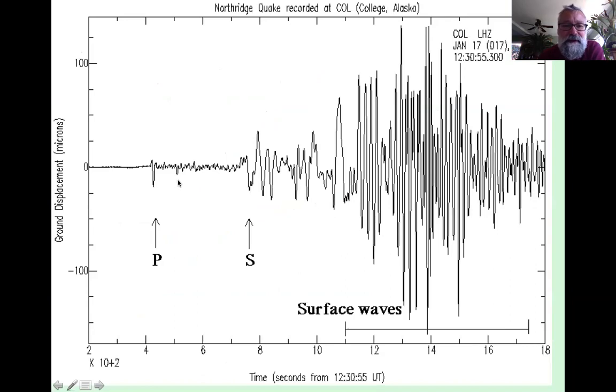This is a typical readout from a seismogram, from a seismometer, and you can see the occurrence of these waves. This is prior to the earthquake. This is the first occurrence of the earthquake, and that's going to be your P wave, because that's the fastest of the waves. It may go up, it may go down, it doesn't matter, but the very first motion, you would look right there where it departs from the horizontal. That would be the arrival of the P wave right there.